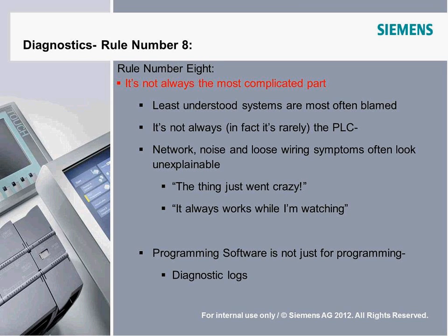PLCs, their mean time between failure, in other words, how often does the average PLC fail, is measured in decades, as long as you don't have an event. So in other words, as long as there's not been a lightning strike or hydraulic fluid hasn't poured into the PLC and so forth, these things will just run. The code doesn't change. The PLC's hardware is just going to sit there and zoom along. What is typically the problem is something connected to the PLC, and that can be the I/O, which is interfacing with the real world, or the wiring, as I mentioned, which is more than half the time.